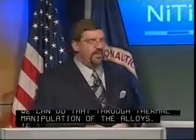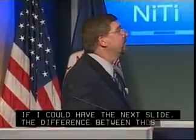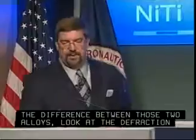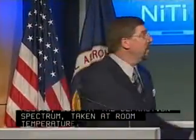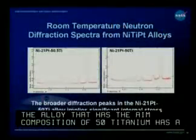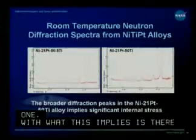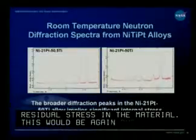The difference between these two alloys, if you just look at the diffraction spectrum, and these are neutron diffraction spectrum taken at room temperature, the x-axis is the same in both of them. What you see is that the alloy that has the aim composition of 50 titanium has much broader peaks than the other one. What this implies is that there's much higher internal or residual stress in the material. And this would be, again, due to these precipitates that we're talking about. So if we have the next slide.